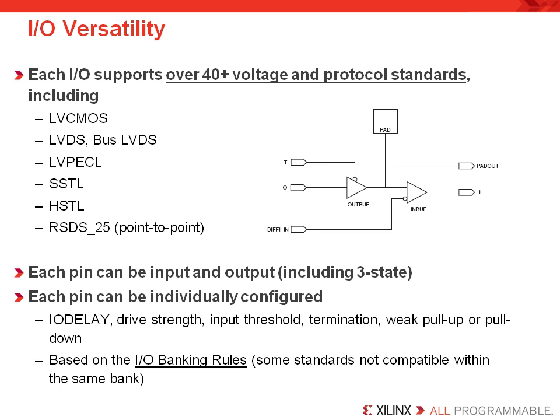However, note that to mix different I/O standards into the same I/O bank, you must be aware of the I/O banking rules. These rules apply because each I/O bank shares the power pins for each of the input and output pins in the bank. Specifically, the VREF powers the input circuitry and the VCCO pin powers the output circuitry. So whichever I/O standards you group into each I/O bank, make certain that the input pins have the same VREF and the output pins have the same VCCO. Now, this is easily planned with the PinAhead utility that's included with the ISE design suite.